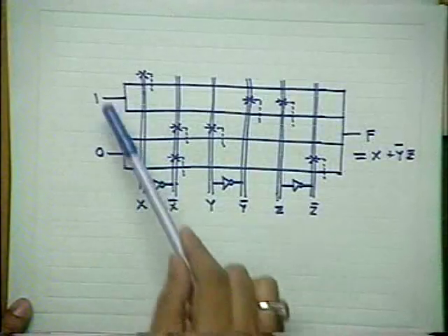After the transistor fabrication and polygate fabrication, I have a MOSFET at every intersection, at node points. Every point has a local short polyline. Then I cover it with an oxide, then etch windows in that oxide only in these locations. Before metallization, I have to etch windows for all these via holes as well as all the electrodes for the terminals, according to the layout of the IC. And then you etch the metal lines, and automatically it will be like this.